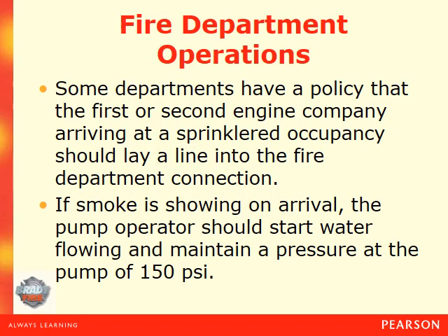Some departments have a policy that the first or second engine company arriving at a sprinkler occupancy should lay a line into the fire department connection. If smoke is showing on arrival, the pump operator should start flowing water at a pressure of 150 psi to support the system. The reason being it's 150 psi is that is the maximum pressure you can apply to the system to get the most water out, or gallons per minute. Once you start going over 150 psi, the pressure causes a reduction in the amount of volume, or gallons per minute, you get.